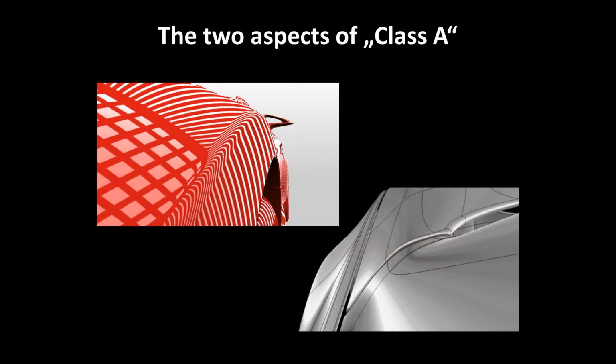And with this Class A model, it is really important to talk about the highlights. Not just the highlights on the continuity, because a NURBS model is a patchwork. It's not only about the continuity between the borders. It's about the inner highlights of a patch fitting to the inner highlights of the neighbor patch, so that everything fits together, so that you can turn off the wireframe and you see an entire sculpture, and you cannot see with the highlights where there was a patch border and where not. And it has to fit engineering criteria. And just then we talk about the Class A surface.